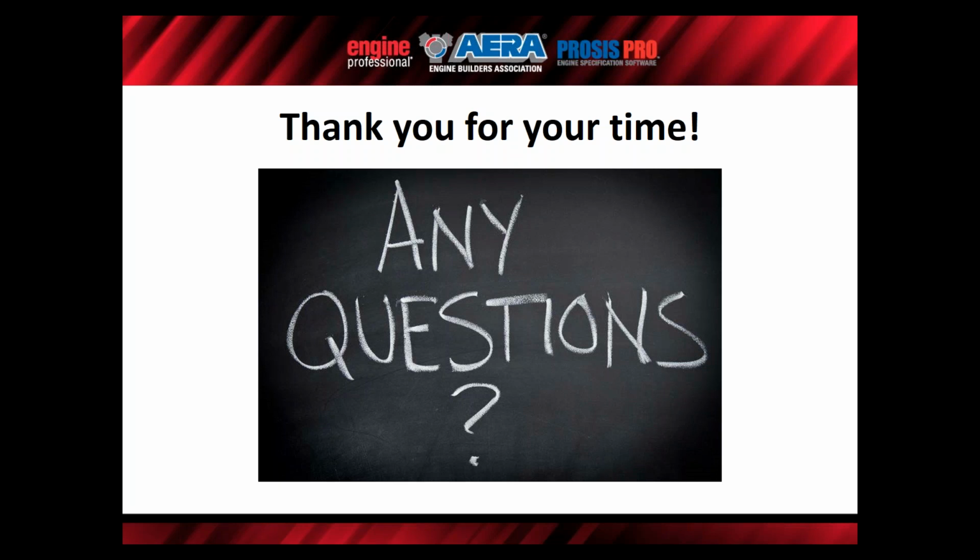Chuck, the question goes, are there seals made specifically for oversized valve stems? Yes, but you have to have some volume, and you have to approach a seal manufacturer and tell them what your plans are. But the answer to that is yes, they can be purchased. You probably are not going to go through your typical parts catalog and find that. It's something you're going to have to make a phone call. That's like many of the oversized OD main and rod bearings that maybe a manufacturer has. Sometimes you just have to pick up the phone because they have chosen not to put that in the catalog.